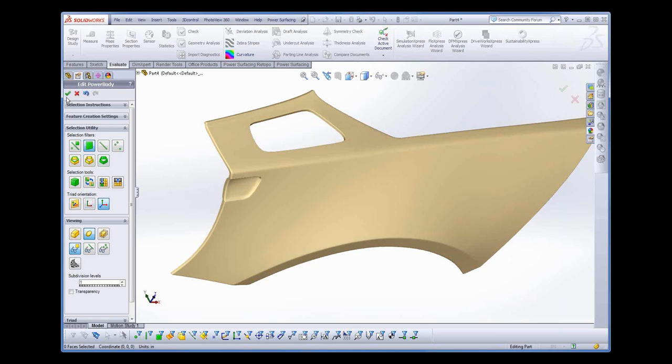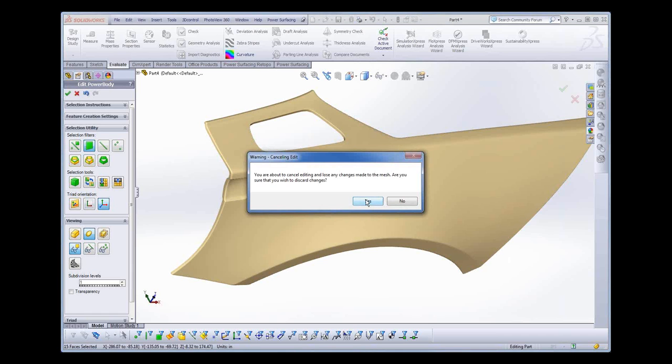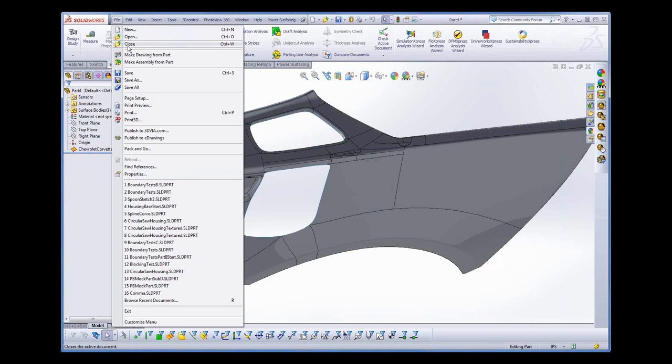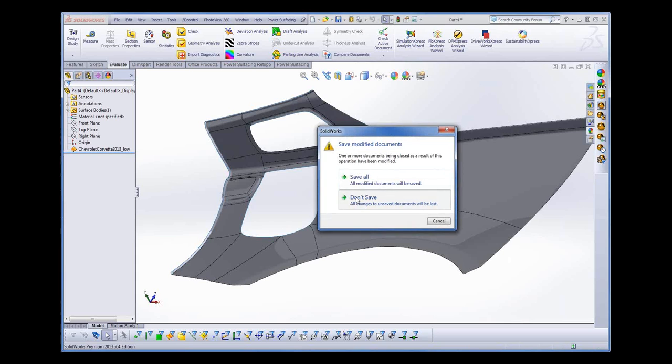Okay. There is one from Vadim. Did we cover that one by any chance? The one at 11:44 a.m. I could read it out loud too. This is from Vadim. I have a question related to the thicken command for surfaces. What does the percentage in the thicken command stand for? For example, if I type -10%, would it be 10% of 1 inch? And if I'm working in millimeters, would it be 0.1 millimeter? Good question. We probably need to change that option a little bit so that it's something other than percentage, and that will be coming in a future release. But it actually stands for 10% of the average edge size.